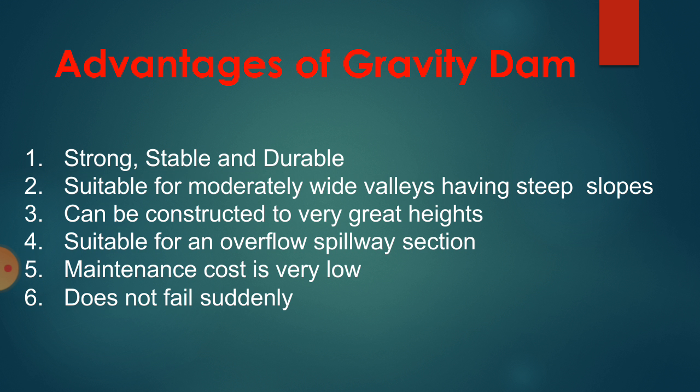Now, advantages of the gravity dam. Gravity dams are relatively more strong and durable than earthen dams. It can be suitable for moderately wide valleys having steep slopes. It can be constructed to a very great height, provided suitable foundations are available to bear the stresses.